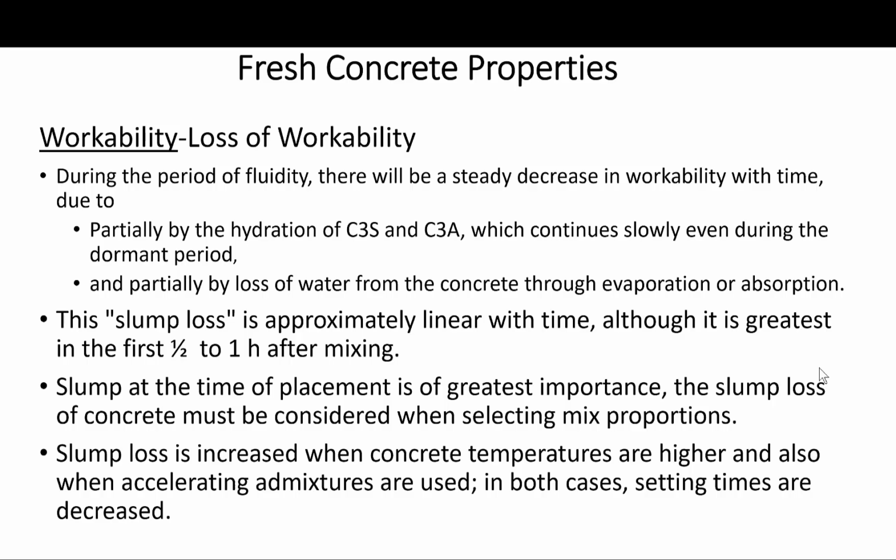During the period of fluidity, there will be a steady decrease in workability with time, caused partially by the hydration of C3S and C3A, which basically continues slowly even during the dormant period, if you refer back to the heat of hydration curve, and also partially by the loss of water from concrete through evaporation and absorption. Also, due to particle interactions, which basically change because of the presence of hydration products on their surfaces.